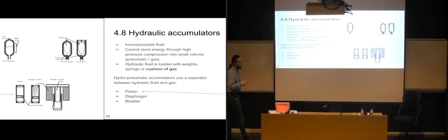And then you have the piston type. There are many ways that those can be constructed. Some use gas, where they have hydraulic fluid on one side of the piston and gas on the other side of the piston. It works in exactly the same way as the bladder: if you start filling in hydraulic fluid at a certain pressure, it's going to move the piston upwards, compressing the gas, and the gas will gain more and more pressure the more it's being compressed.